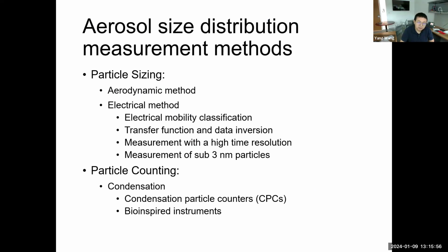And as a summary, in this session, I talked about the particle sizing and counting methods. In sizing, I introduced the aerodynamic method and electrical method, especially regarding the proper usage of the SMPS system. And then on particle counting, we talked about the CPC and the condensational methods, and an array of other instruments that are using the condensation mechanisms.